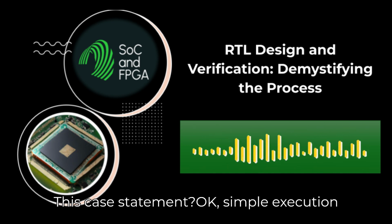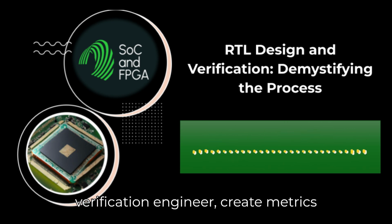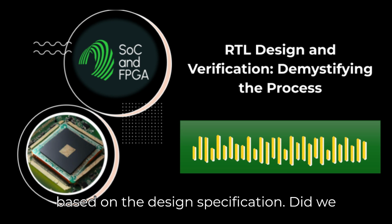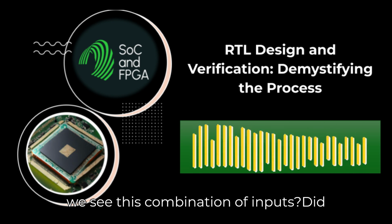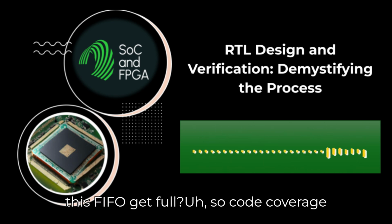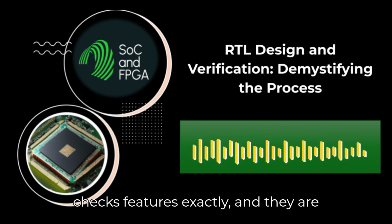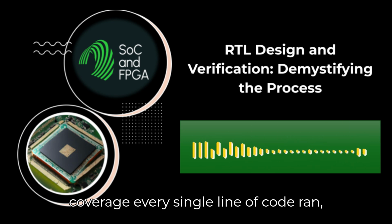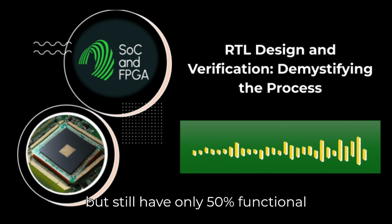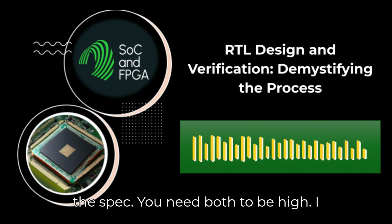Okay, simple execution count. Right. But then there's functional coverage, which is user-defined. You, the verification engineer, create metrics based on the design specification. Did we test this specific mode of operation? Did we see this combination of inputs? Did this FIFO get full? So code coverage checks the code, functional coverage checks the features. Exactly. And they are complementary. You could have 100% code coverage, every single line of code ran, but still have only 50% functional coverage because you didn't actually test all the critical features described in the spec. You need both to be high.